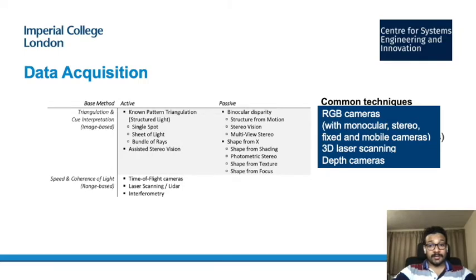Data acquisition methods in the context of scan versus BIM could be classified as triangulation-based methods or time-of-flight-based methods. And they may also be classified as passive methods or active methods. The active methods, such as the time-of-flight-based methods, use light or radio wave emitters to register distances to or outlines of an object, while passive methods like triangulation work with reflected light waves of the respective objects.